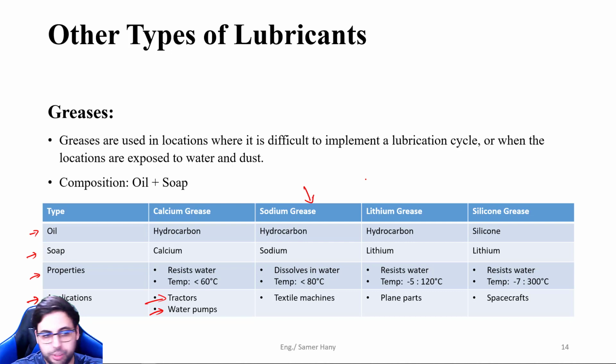The third type will be the lithium grease. This lithium grease is just hydrocarbon oil with lithium soap. This is much more expensive than the calcium and sodium greases, but it resists water and withstands higher temperature than both of these previous greases. But since it is much more costly, it's used in plain parts.